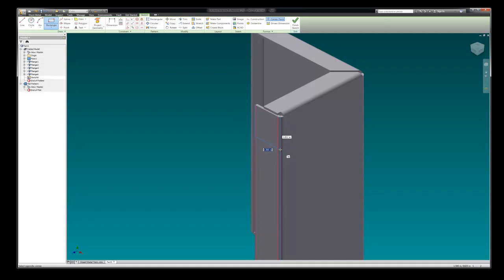You can see the blue one is there at 1.5, so I could just hit Tab, type 1.5 and then Enter. Great, that's how I did it. I can also double click on this and make this 2, or make this 6. So you have that ability to change that at any time. Again, we have the little drop down arrow here, and I can go back to my 1.5 and hit the check mark. Now when you're done with a sketch, you always pick Finish Sketch.